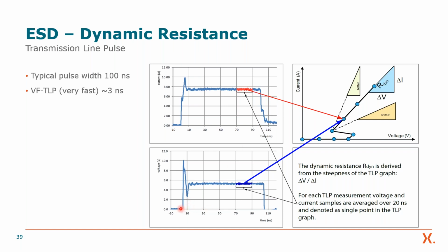In the voltage, you see something similar. This is the voltage across the ESD protection device, and you see an overshoot, like with the clamping measurement. Then the device is activating and coming to steady state voltage. What is done is that you excite the ESD protection device with increasing amplitudes of the rectangular pulse.